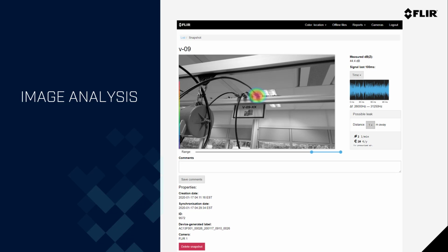So here's just an example of output from the system itself. You can see the data that we capture and display. You see a very large image, and as indicated by the color scale, the intensity of the sound that we were able to detect. And you can even see where the system itself can calculate the size of the leak and provide savings estimates that you can add to the display. It's all editable, at your leisure, in terms of annual savings from fixing the problem itself.